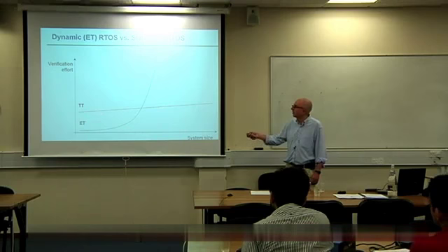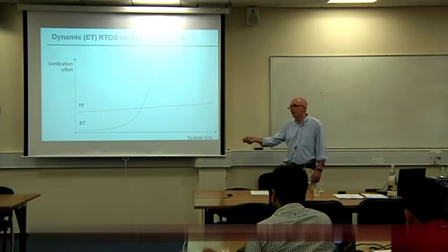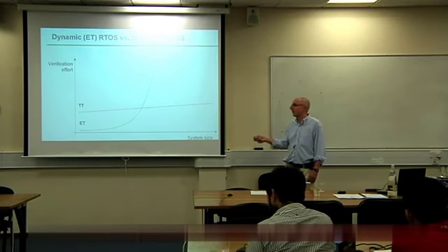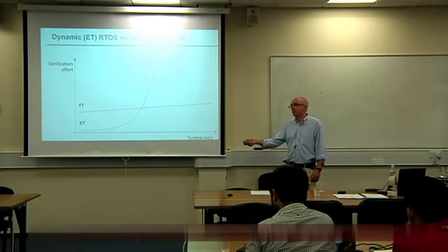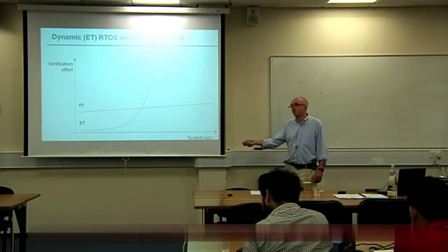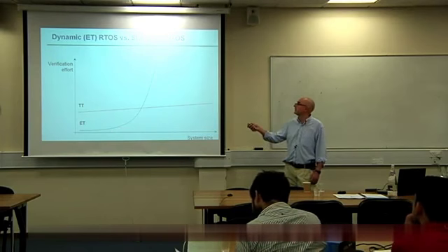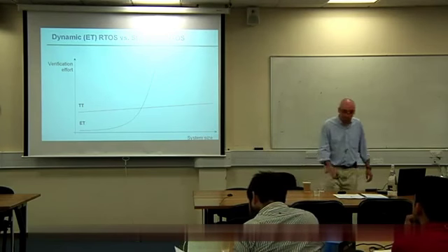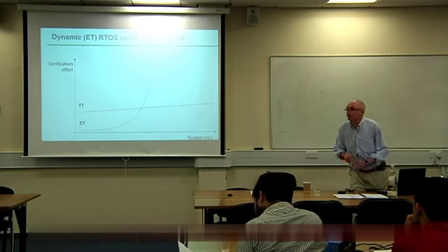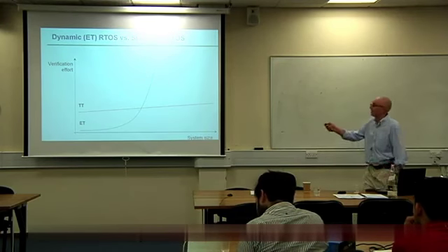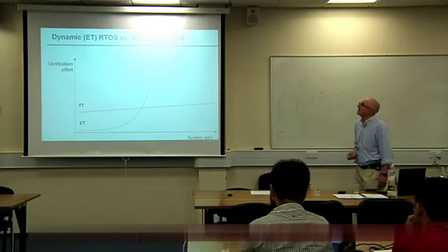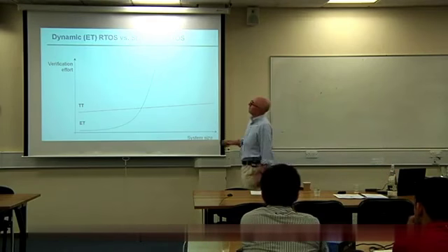And the overall cost of building a TT design and verifying it doesn't go up very steeply. It's cheaper and simpler to build a small event-triggered design, because you just have to hook up a few interrupts. As you gradually build this thing up, the verification effort for these event-triggered systems then goes through the roof. Happy to argue this through. There's plenty of MSc projects in this area, if anybody wants to explore some of these points.